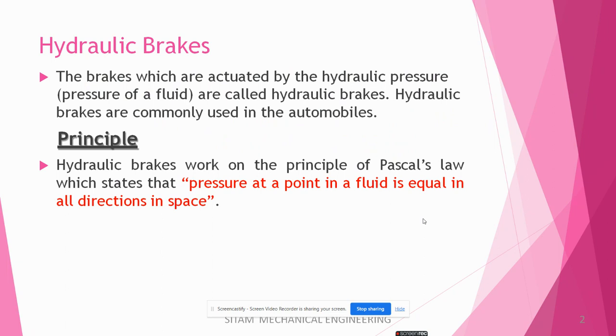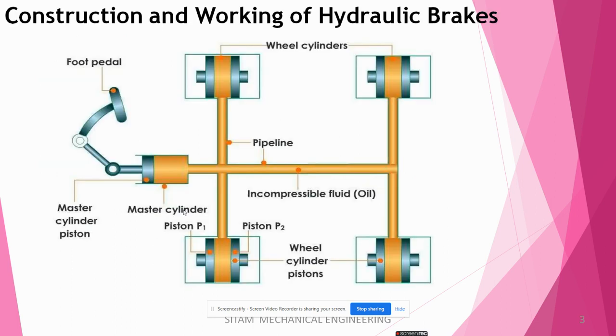The hydraulic brakes work on the principle of Pascal's law. As we know, Pascal's law means the pressure at a point in a fluid is equal in all directions in space. According to this law, when pressure is applied on a fluid, it travels equally in all directions so that uniform braking action is applied in all four wheels. This is the principle of hydraulic brakes, and this is the construction and working of hydraulic brakes.